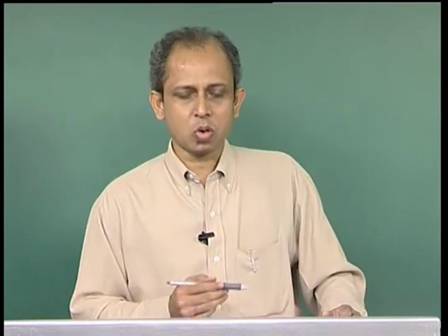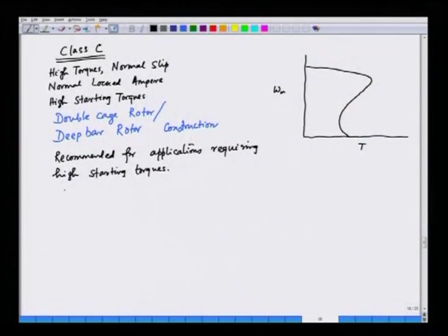On the other hand, the starting torque is quite significant because of higher starting power factor, and hence this class of motors is employed in loads like punching machines and presses and things like that. So now we will see the class D motors.